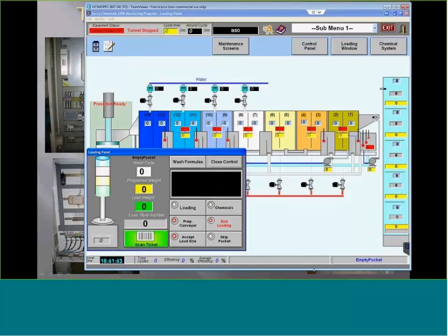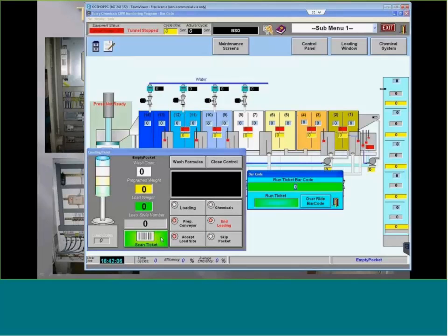All of our systems use a barcode scanner. I use a Symbol wireless scanner that is connected directly to that industrial PC, reporting directly to InduSoft. Everything that's scanned in, on average a 16 to 20 digit barcode, is recorded as data, and it's going somewhere and being used for other purposes.